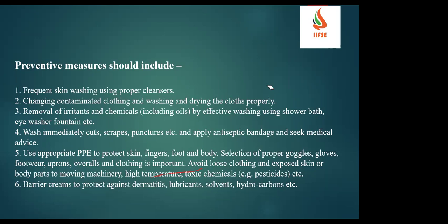Then wash cuts, scrapes or punctures immediately, apply antiseptic bandages and seek medical advice. Why is it required? Chemicals have a tendency to go inside or come in contact with our bloodstream. If the skin is damaged, it is easier for the chemical to go inside our body.